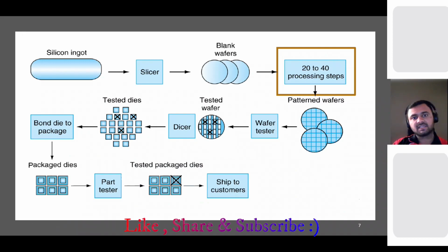Okay, so how is it fabricated? First, it's fabricated from silicon, like sand, by foundries such as TSMC, Taiwan Semiconductor Manufacturing Corporation, or Global Unichip. There are many foundries based in Taiwan and the US. I think even Intel has its own foundry. Basically they use sand as the basic material, and they use some method to grow that as a crystal, and then the crystal will be very long. Nowadays I think it's 9 inches or more, and then they will slice it, and once they slice it, they will get these blank wafers.